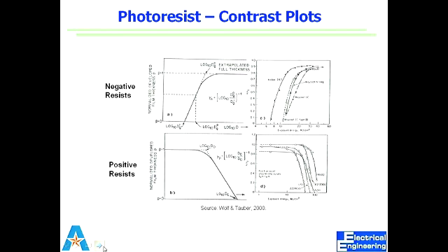But the bottom line is that at the end of the process, we see that at a given energy, the ratio of exposed region to unexposed region is much steeper. Above this energy, you can get the whole region exposed very quickly with respect to the thickness, which would make our sidewalls much steeper.